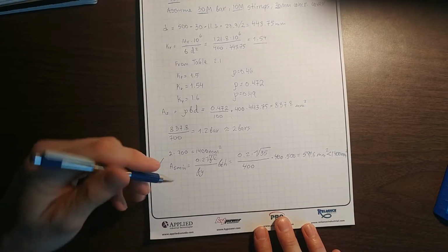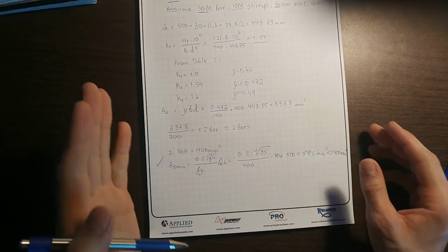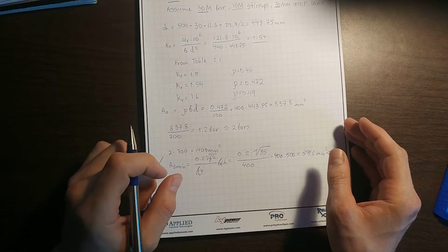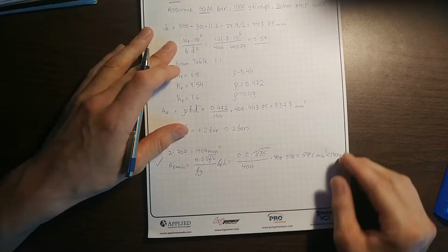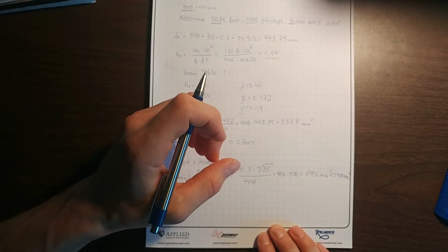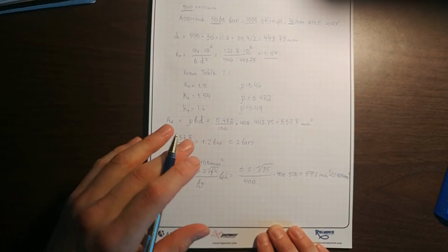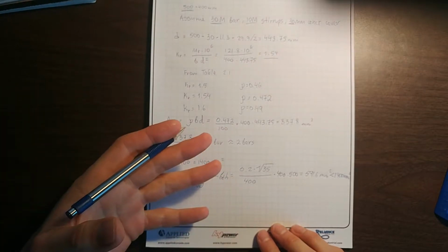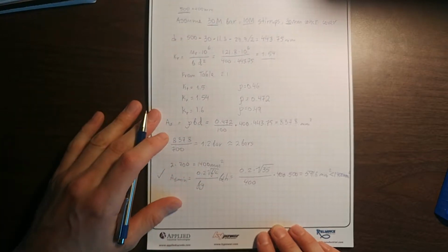The second check you want to do is spacing. You want to make sure that you have enough width that when you put those bars in the beam, you're going to have enough room for the concrete to flow, because concrete is not just liquid, it has aggregate fractions of different diameters, and you want to make sure those rocks can freely flow between the bars, and there is not going to be any air in the concrete beam, because you don't want any spaces or air pockets in the beam once it's cured, right?